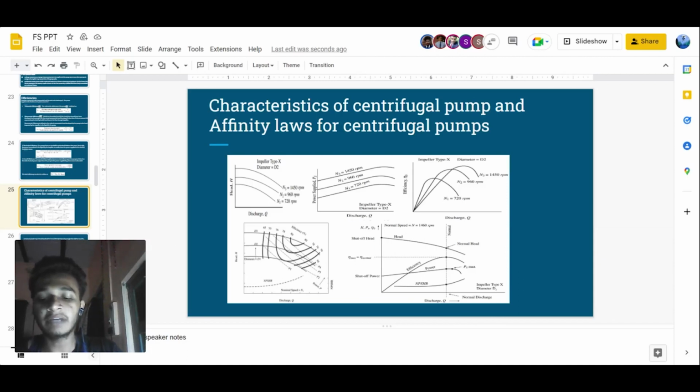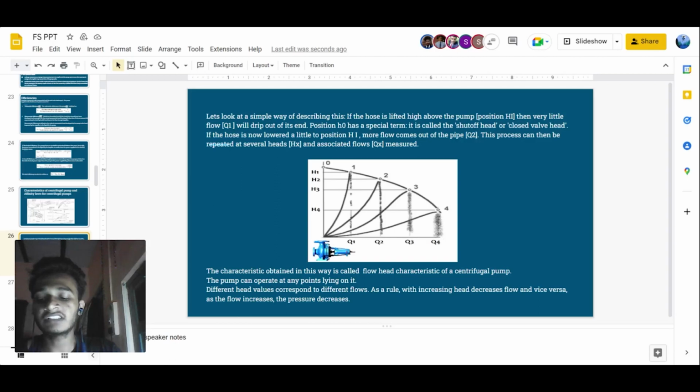Operating characteristics of a pump are the constant speed characteristics of a given type of pump of fixed geometry. This is essentially the set of curves consisting of head and flow rate curve, power and flow rate curve, and efficiency and flow rate curve, all belonging to a prefixed value of speed n, all extracted from the main characteristics curve. It often comes as a surprise that pump flow and pump head can be related, however, each pump has its own characteristics and the relation is different for different pumps.